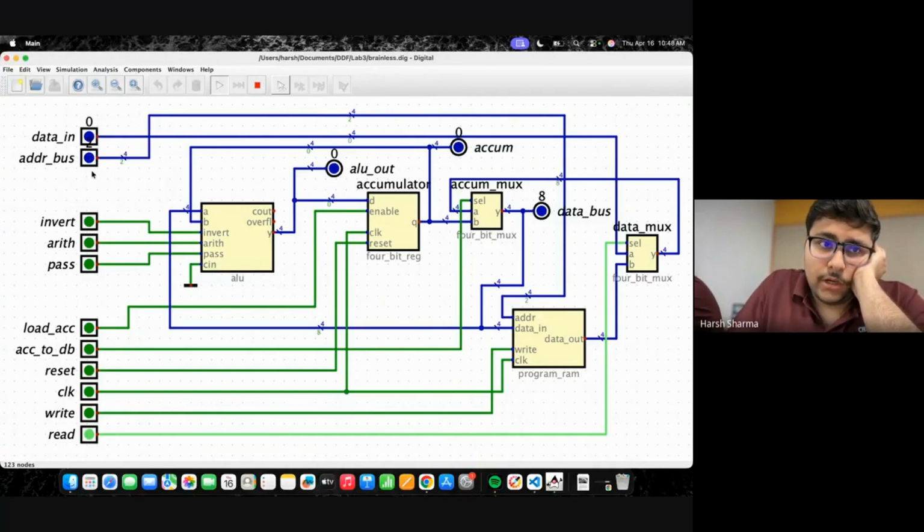Now let's see the subtraction. Now let's take it again 0. So for subtraction, we see the 0 goes here, address bus, it gives 3 as output, 3 goes here into B, we want to display B, we have taken select line 1, we read the output as B, which is 3, 3 comes here, select line is 0, we get 3 at the output, this 3 goes all the way back to A. Now we have 3 at the ALU where we wanted it, but let's store it to B, so we just pass it as the output, we get ALU out 3.